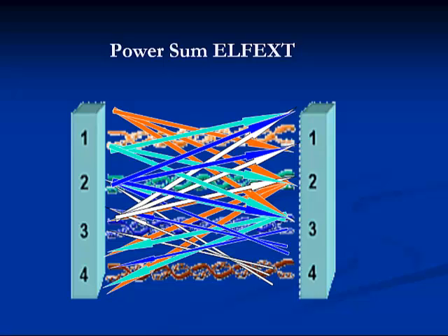The calculation describes the ratio of disturbances to the level of the desired signal. It is another indication of signal-to-noise ratio. Another way of looking at it is that the value represents the ratio between the strength of the noise due to crosstalk from the far-end signals compared to the strength of the received data signals. Each pair-to-pair combination is measured as the attenuation on each pair will be slightly different. If the equal level far-end crosstalk value is very high, it may indicate that either excessive attenuation has occurred or that the far-end crosstalk is higher than expected.